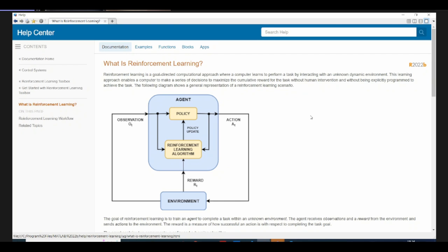This one is a little bit complicated. There are two parts over here. One, the shoulder and the elbow can take its own decision. The shoulder can move in this way, the elbow can move in this way. Both can move in one direction. It's a choice. But based upon its own decision as it moves, whatever the end effector position is, it will be calculated against the target position. So target position XY and end effector position XY.